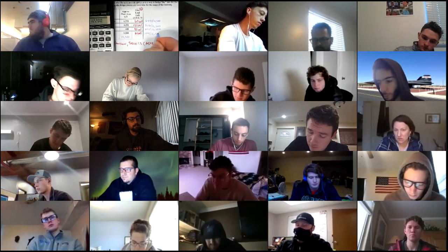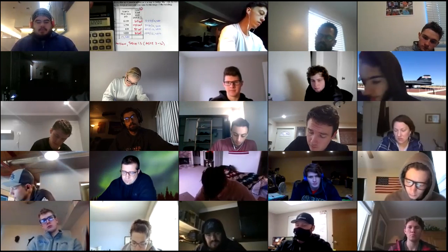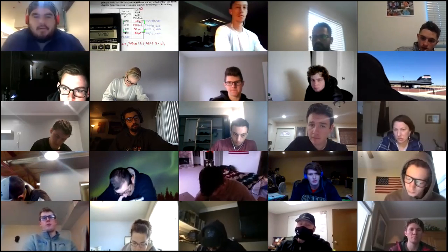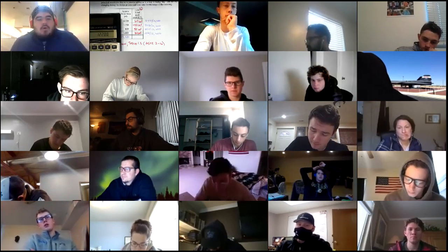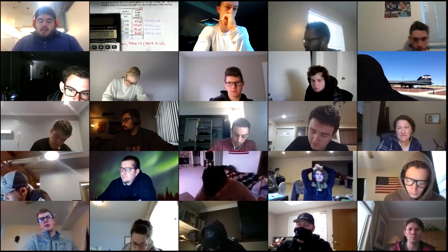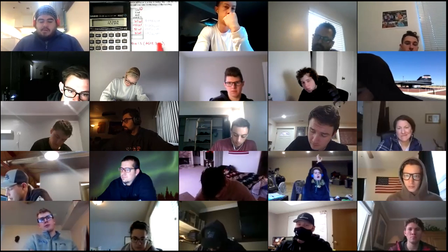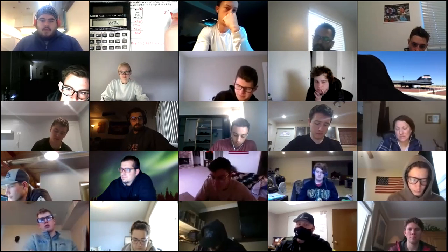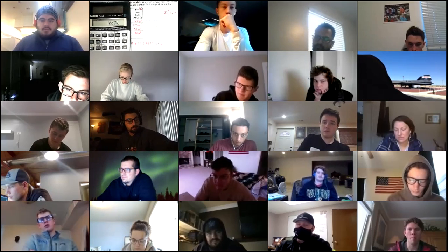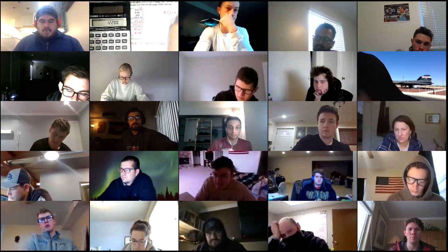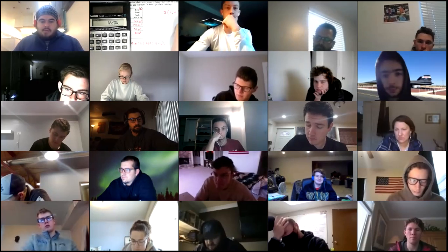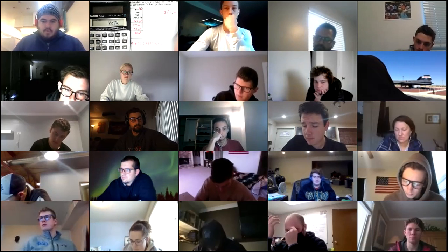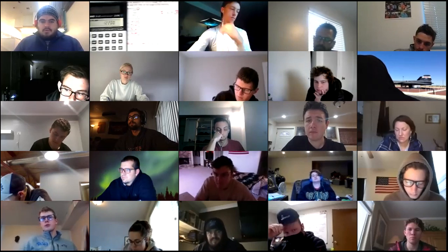And rather than actually computing that number, I'm going to multiply this weighting factor times that value there, and then we'll just add it all up. I'm going to be dividing by the 12,200 each time, so I'm going to factor that out. So what I'm doing is taking the sum of the load times the space, divided by the total space.